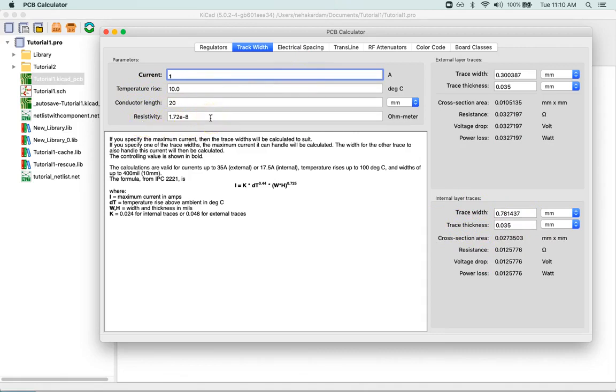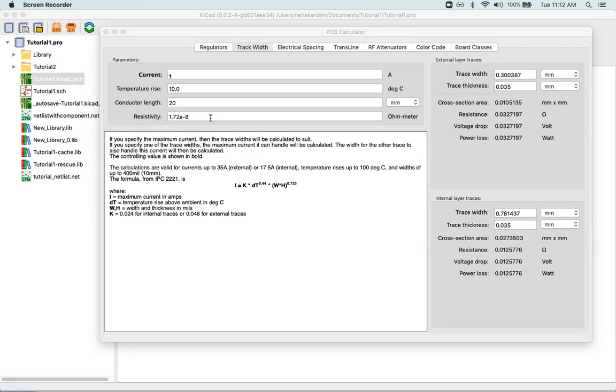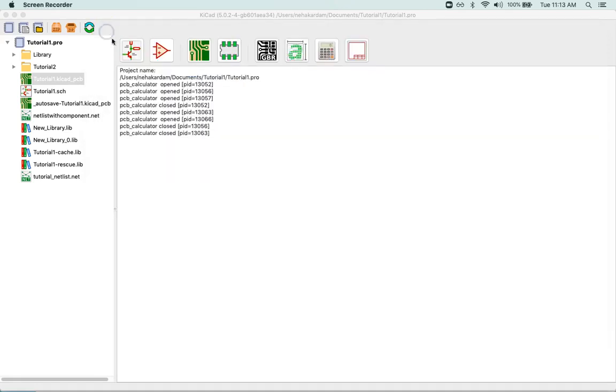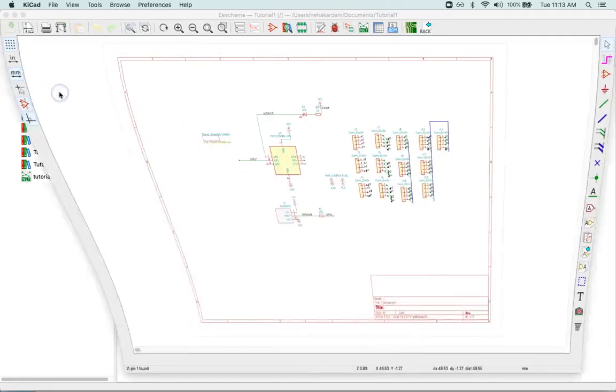So this is how you use the calculator on KiCad. And also you can change the dimension over here if you want in centimeter, inches, mils, etc. You can use that, same as here. So there are so many options given on your KiCad, and you can utilize that to create your schematic with appropriate dimensions. Now what we're going to look at next is annotating the schematic, and for that I'll take this example.